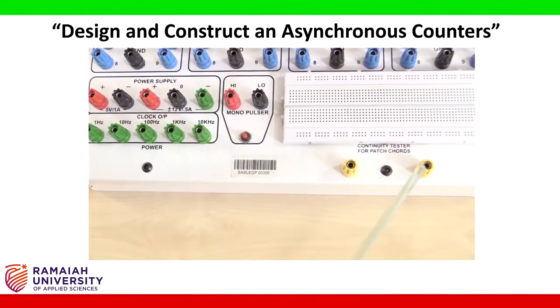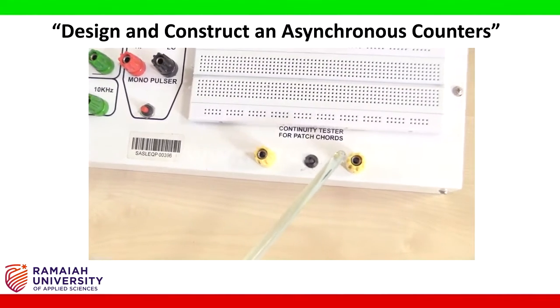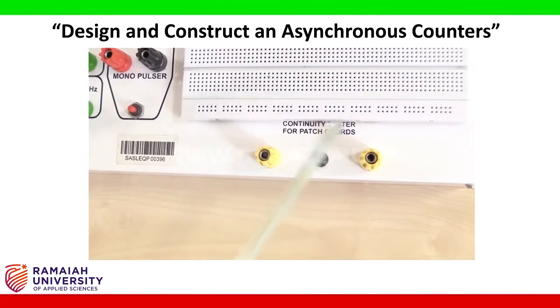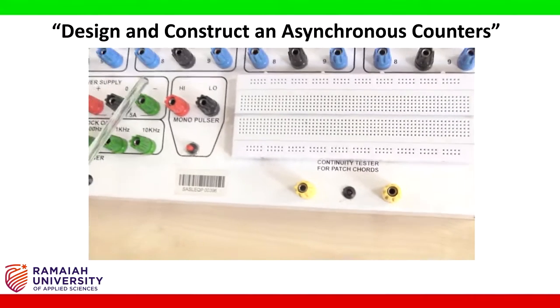And here you can see there is a continuity tester to check the patch cord continuity. So by placing the patch cord here, if you get a beep, that means the patch cord is working fine. So in that way we can check the patch cord's continuity here. So this is about the digital IC trainer kit.